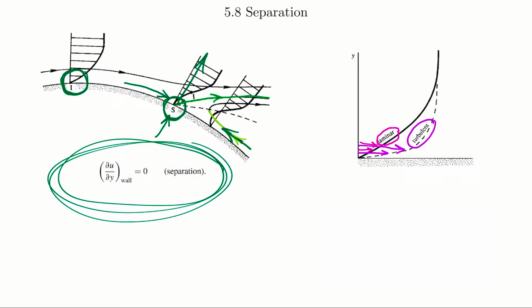We'll see in the following section on specific shapes exactly where these separation points occur, because this is a really important phenomenon, especially for drag force. What happens is after it separates, the pressure downstream tends to stay at the value it was at where the separation occurred, so it stays fairly low. So this low pressure at the rear of these bodies tends to pull back against it. You could think of a vehicle that's trying to drive: where the flow separates, you'd have a low pressure zone at the back, and it would pull back against it. That drag force is also known as form drag.